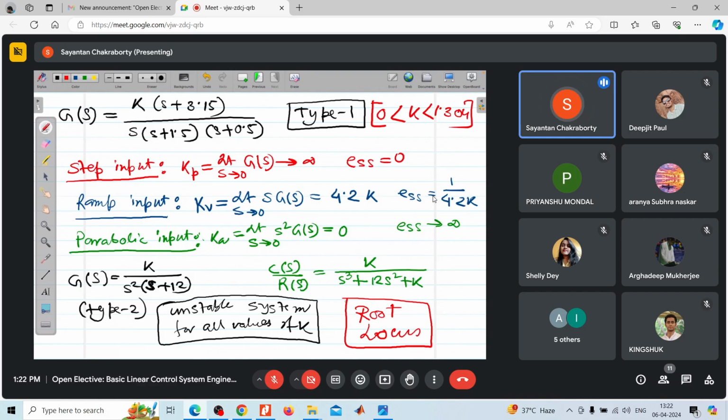That is, you find how the roots of the closed loop characteristic equation vary with respect to a variation in a particular parameter, in this case the gain, graphically, not analytically. You do not have to calculate the pole location for each and every value of k. There are certain rules that give you a graphical representation of the locus of all the roots. From that, you can calculate the operating range of k for which the system will remain stable. So the root locus plays a very strong role in determining the range of stability.